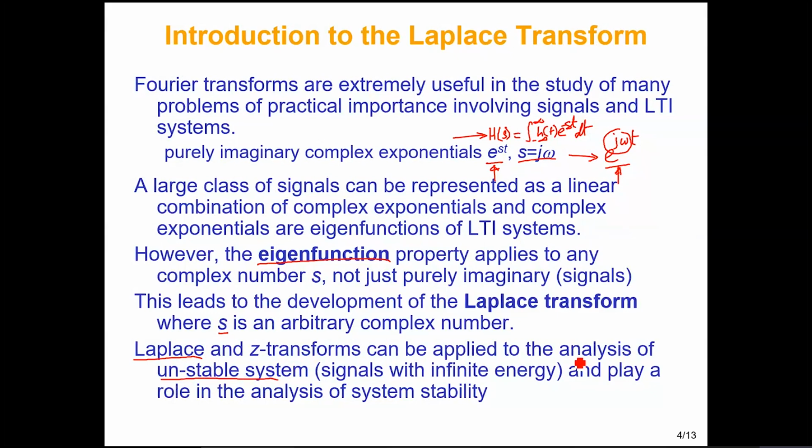Generally, if you want to find out whether a system is stable or unstable, we do Laplace transform and find out about the stability. It is again valid only for continuous time. The equivalent that we have for discrete time is the Z-transform, which will be the last topic of this course, but it will come later.